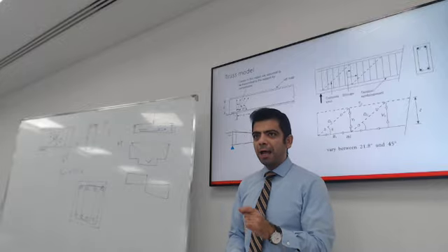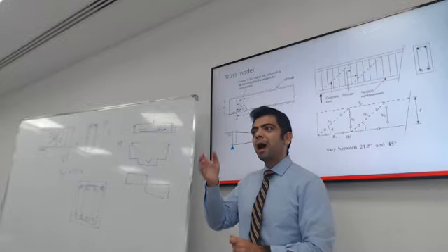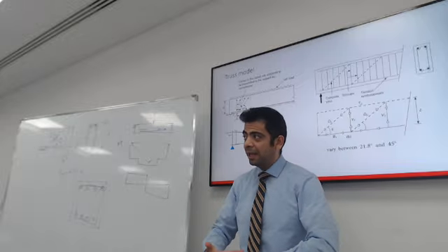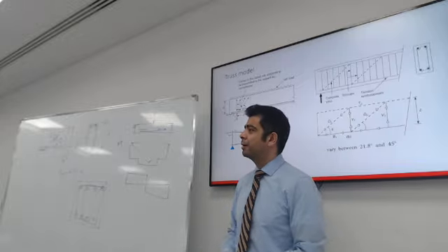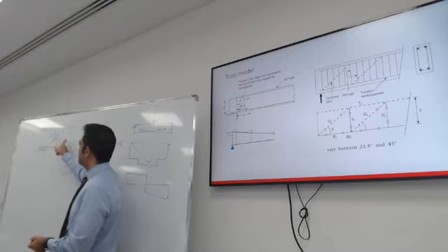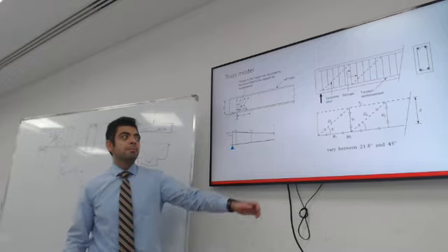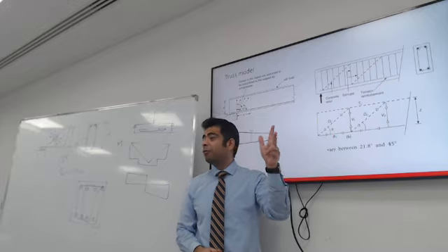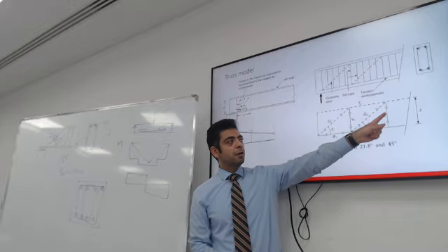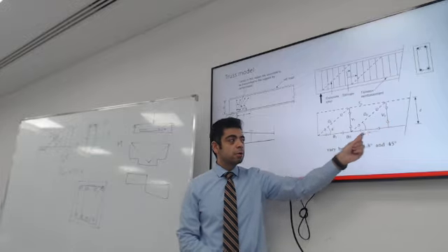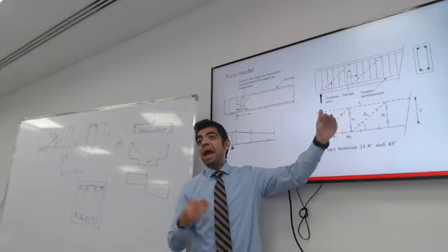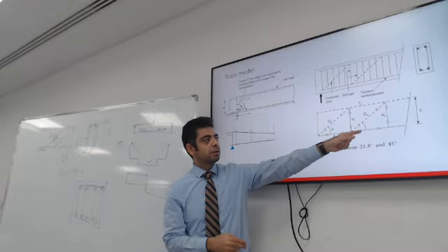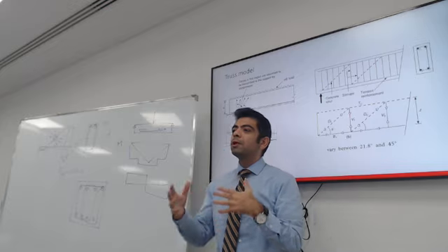If there is one thing I need you to understand about this point, it is that high shear forces could result in additional tension in the bottom horizontal rebar. Not all of the shear can be resisted by the stirrups, because the shear model has three components: a vertical force in the stirrup, a horizontal force in the bottom reinforcement, and a compression in the concrete, the compression strut. And this compression strut angle is within the range we talked about.